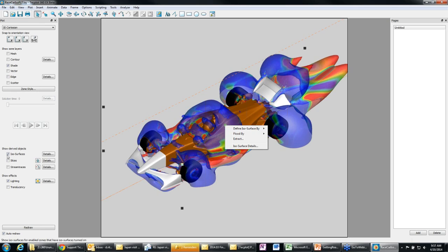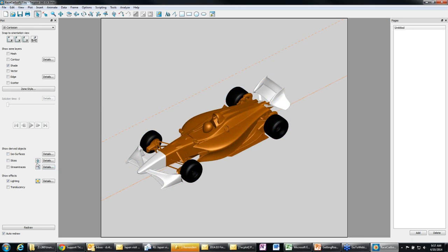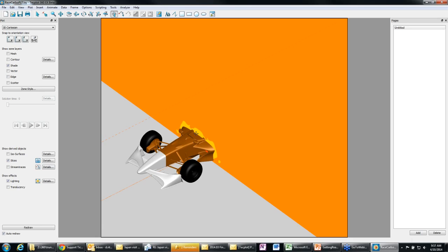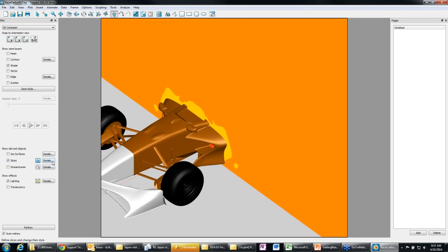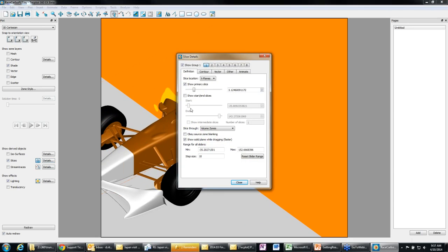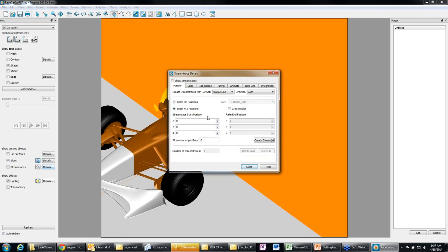Usually what we do is we put them on a plane, right? If you seed it on the surface, it'll stay on the surface usually, or sometimes not move if there's zero velocity there. But if you put it on a slice plane in the field around the object, then you'll get stream traces.